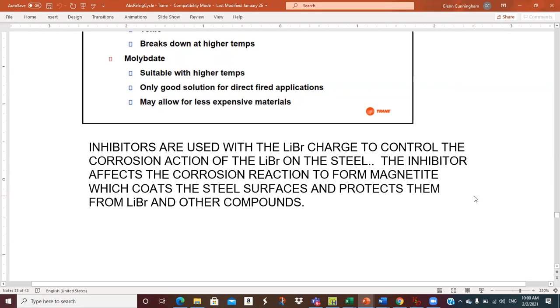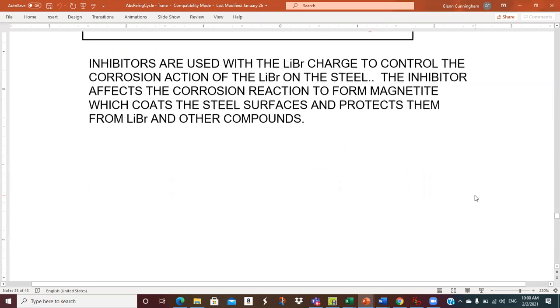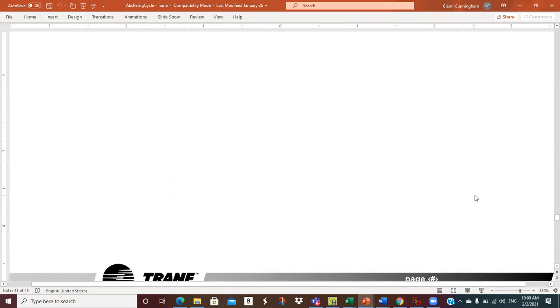Then when you fire the unit back up again, the steam lines get hot and the steam takes all that cracked up magnetite through the turbines and causes damage on the steam turbines. Not that you guys are worried about that, but anyway, magnetite shows up.